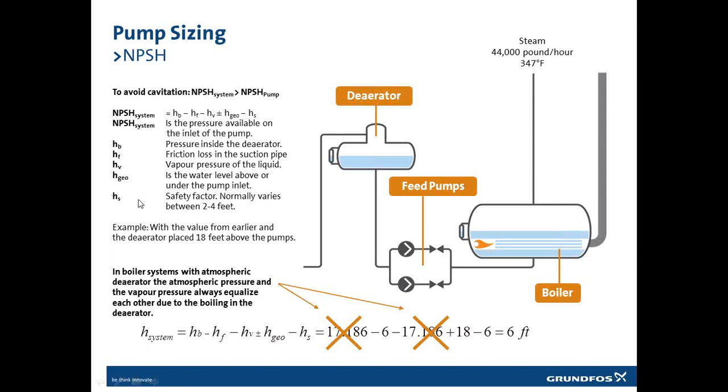And that is the one, if we are in doubt, put on 2 extra feet so that we add 6 feet in safety factor. I think for the audience, if you're looking at a CR pump data booklet, there's a worksheet where you can actually calculate NPSH, and I think in our example, our recommendation is to use 2 feet as the safety factor if you're utilizing a Grundfos CR data booklet or CR product guide.